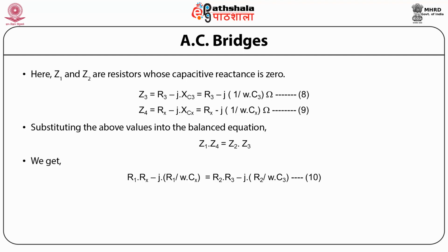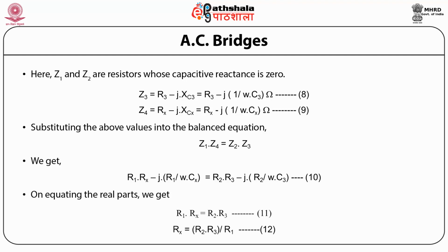This is equation 10. Equating the real parts, we get R1 dot Rx equals R2 dot R3. This is equation 11. Rx equals R2 dot R3 divided by R1.